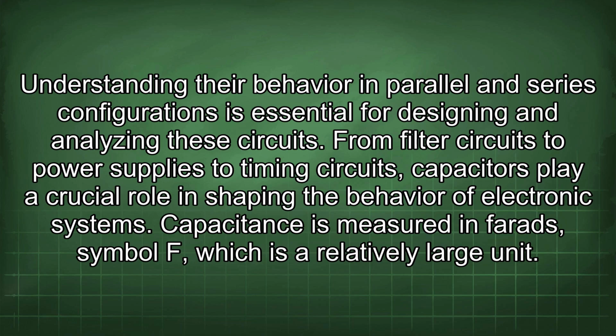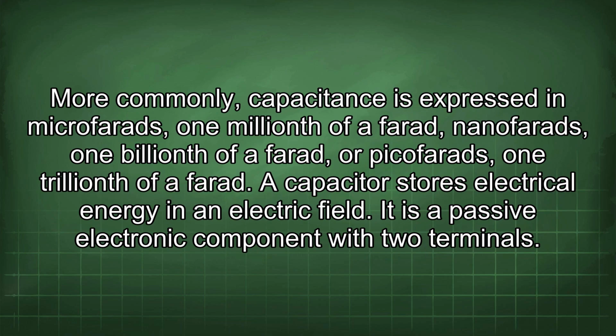Understanding their behavior in parallel and series configurations is essential for designing and analyzing these circuits. From filter circuits to power supplies to timing circuits, capacitors play a crucial role in shaping the behavior of electronic systems. Capacitance is measured in farads, symbol F, which is a relatively large unit. More commonly, capacitance is expressed in microfarads, 1/1,000,000 of a farad, nanofarads, 1/1,000,000,000 of a farad, or picofarads, 1/1,000,000,000,000 of a farad. A capacitor stores electrical energy in an electric field.